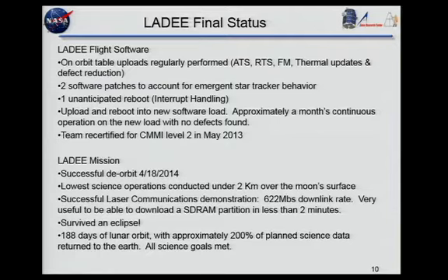In particular, that Star Tracker, who joyously gave us all those images, also gave us a lot of trouble whenever it got close to the moon's, whenever it got close to looking at either the moon or the Earth, it just took one look at a big bright object and went, oh, I'm going to delay my quaternion estimate for you. So we had to patch our state estimation system in order to ignore those delayed quaternions and errors in the quaternion returned when we were getting close to the big bright object.